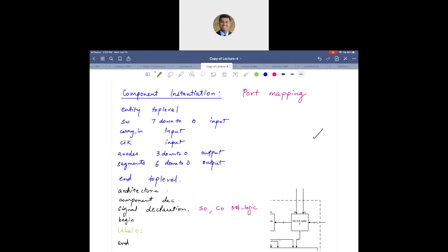In this case, I'm going to say bit full adder, provided this is the same name I used for it in the component declaration, followed by port map, followed by parentheses, semicolon.